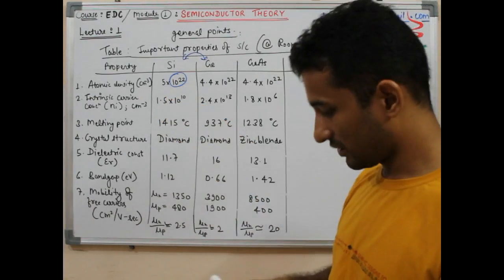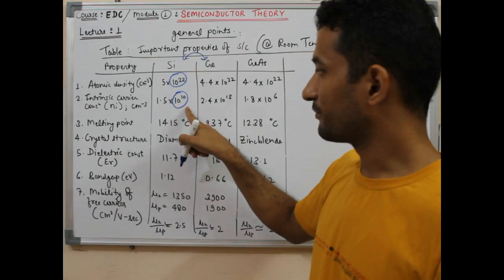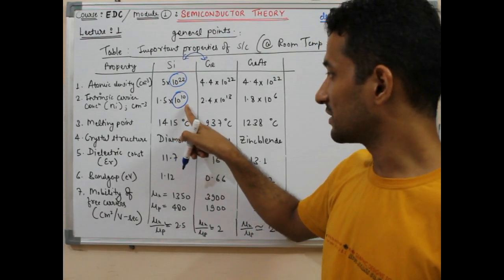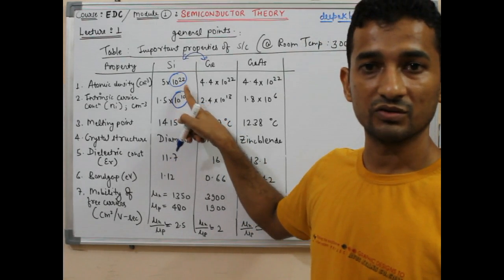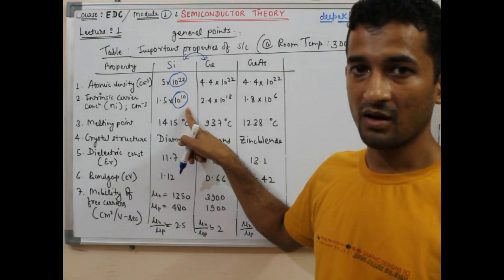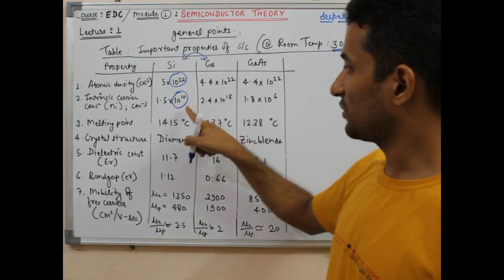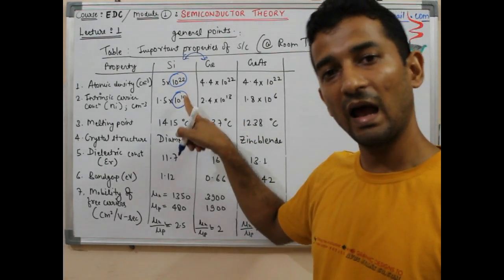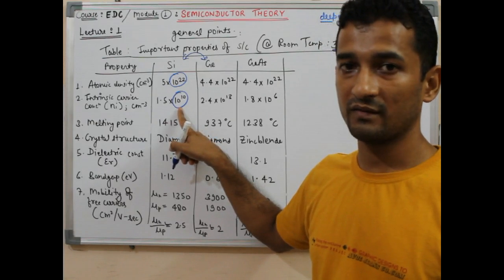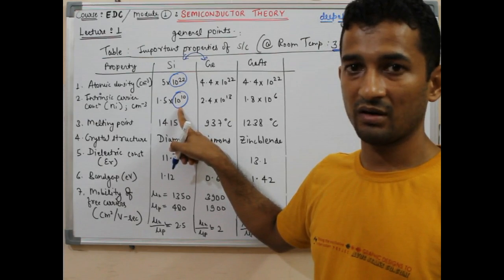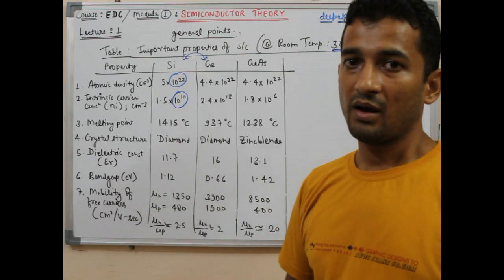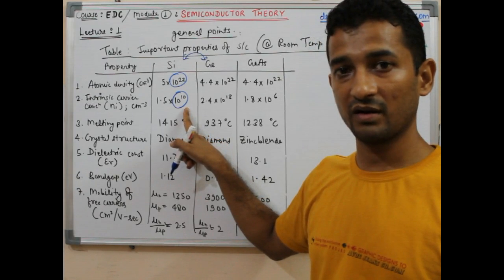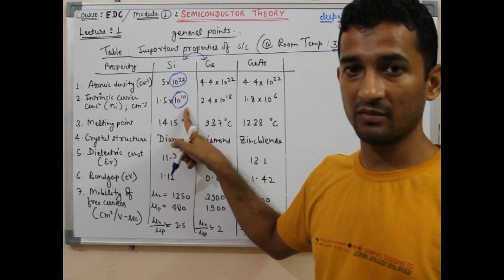Again, I am reminding you that this figure may appear misleading because it looks like a large figure, but it is negligible in front of this. So this is a very poor number at room temperature. At room temperature, this is the free carrier concentration. These many electrons and free holes are available in the conduction band. They are ready to move and they are moving randomly. But because this is a very small amount, we cannot get an effective or sufficient current out of it in commercial applications.